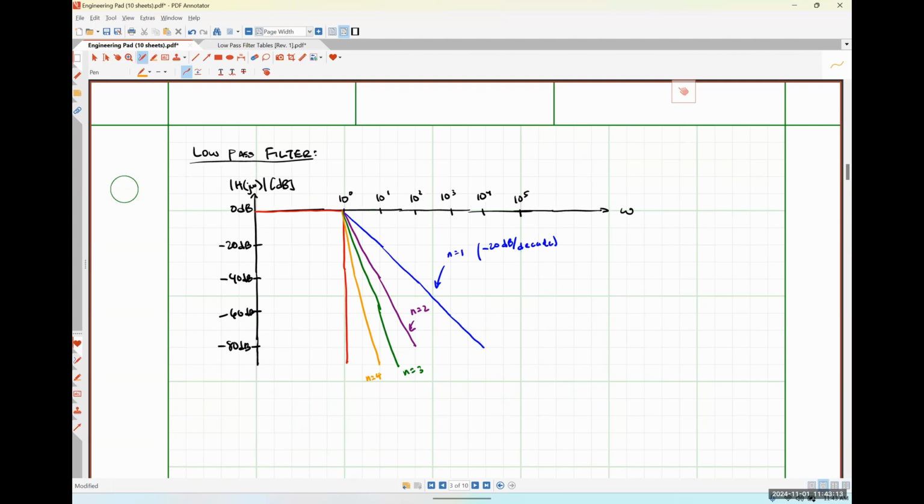So not really. Let me rephrase that. For the Butterworth topology and the Chebyshev and the Bessel filters and all of that kind of stuff, you are not losing any attenuation other than the ratio of the source resistance to the load resistance. That's the only attenuation we worry about there. Everything else is energy storage elements. So as long as we're not putting in a ton of power so that we have large losses, we should be fine.